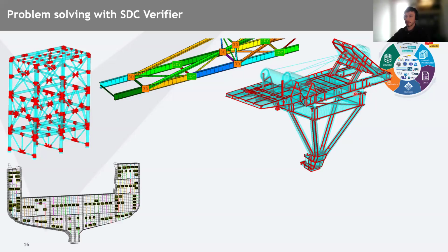Another part of the recognition is stiffener recognition. All the beam stiffeners which are modeled within your FEM model will be recognized. Each of them will get a separate ID number, which also allows us to easily recognize which element has a certain utilization factor, and pick only certain members of our model which we would like to optimize, so we don't have to do it for the full structure.